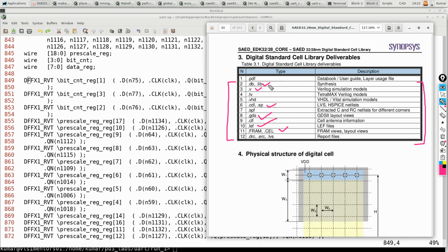Now coming to your question, we have talked about the drive strength part. That depends on your timing requirements and area requirements, so the tool might pick. And the device type also, HVT, RVT, ULVT. Your VT flavors are chosen based on your timing and leakage power requirements.